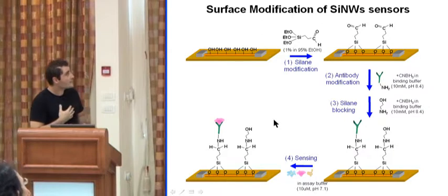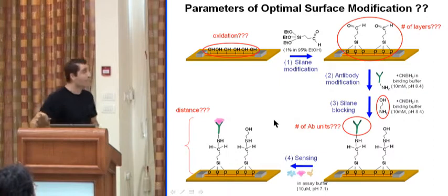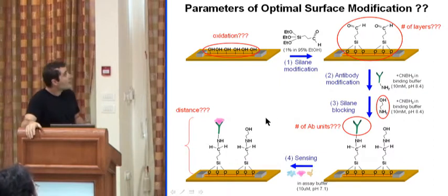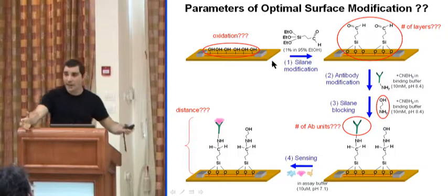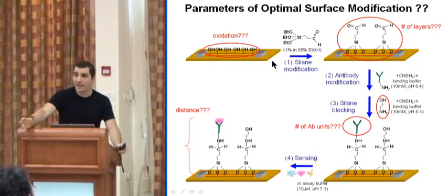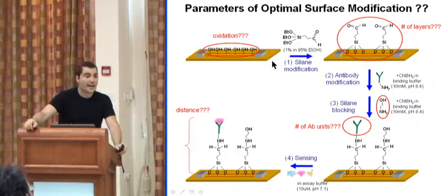So this scheme shows the chemical modification of devices. Here we have a device, 2 electrodes, a single nanowire, silanol groups. So the first step is to bind a monolayer or a very thin layer of a chemical component, a functional component, on the devices. We would like today to be able to modify this chemical layer only on the silicon nanowires and not around the silicon nanowires.